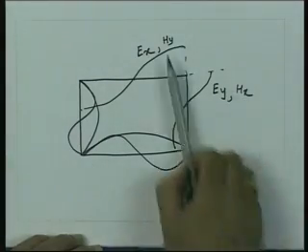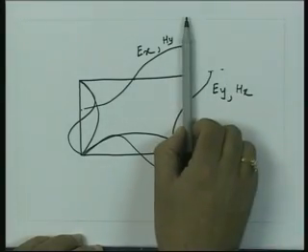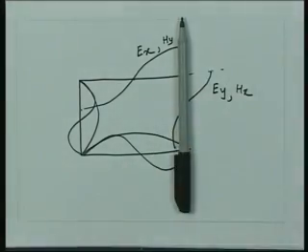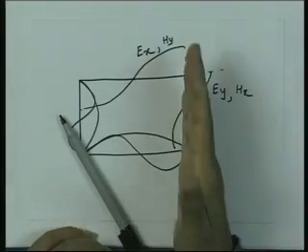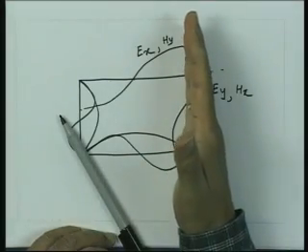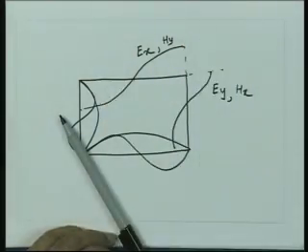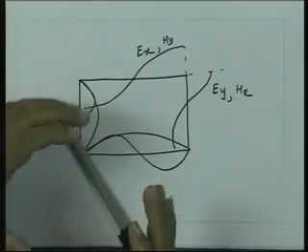Of course, the tangential magnetic field, whatever is there on the boundary, is balanced by the surface currents. So, there is no boundary condition on the tangential component of the magnetic field. So, essentially by using this observation that the tangential component of the magnetic field is maximum on the conducting boundary, and having understood that the solution gives me a sinusoidal variation in the transverse direction, now we can readily write the solution for the transverse electric mode without going through the same analysis.